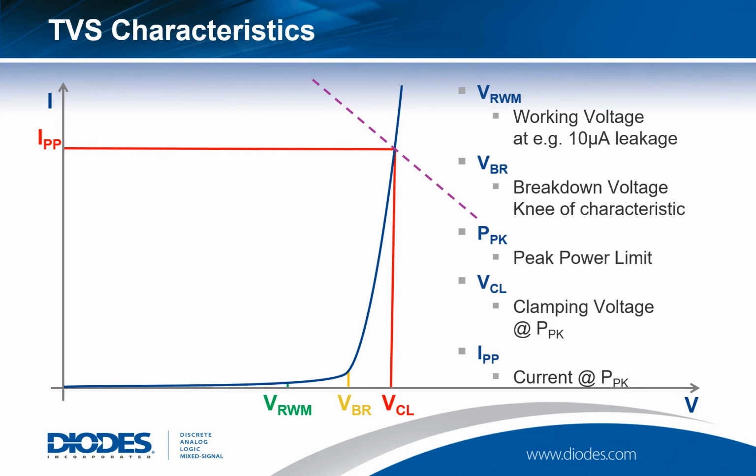If we now bring in our protection margins from the previous slide, you can see how we want to align some of these characteristics to the margin that we might have. It's important to note that you can put in a 5-volt TVS onto a 5-volt rail. You understand that the 5 volts reverse working voltage means that you have a maximum leakage that you'll be dealing with.